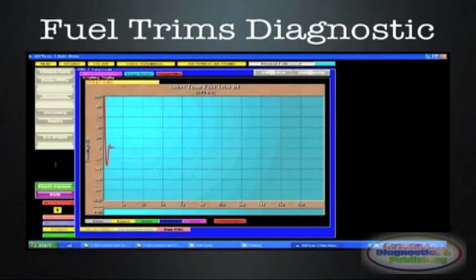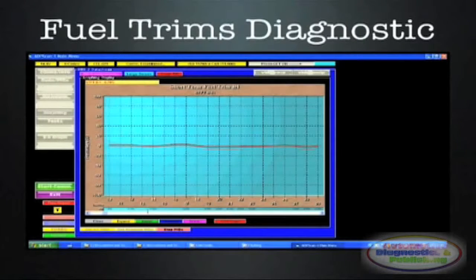After testing your O2 sensor, then you're ready to concentrate on the fuel trims. The short-term fuel trim is fast reacting, while the long-term is very slow, meaning that this PID reacts to the more persistent air-fuel imbalance. Use the short term to check for vacuum leaks, together with any other technique, such as propane enrichment using the right tool.